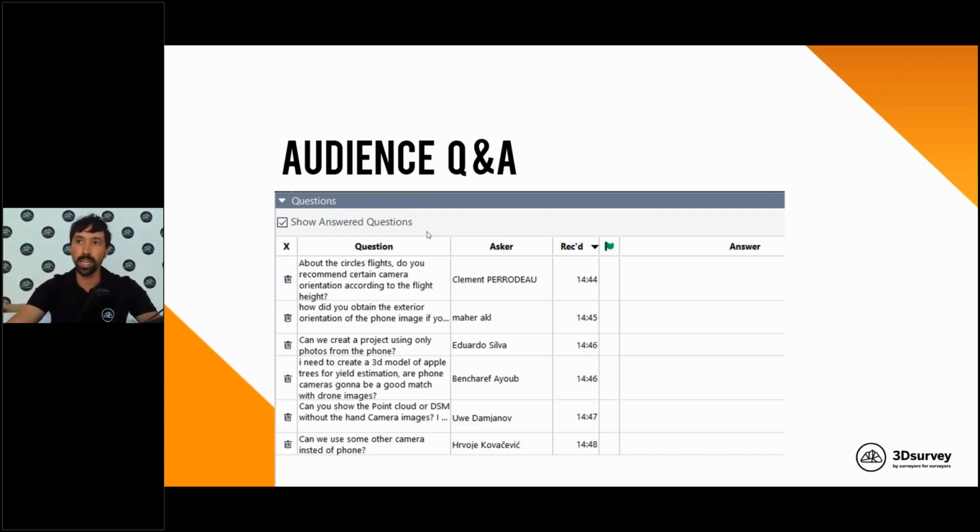You could put 5 targets on the building facades and measure them with a total station or something like that. This would be an area of 5 by 5 meters. Then you trigger about 50 images in a grid, a vertical grid, of course manually, and you do the processing, you do the bundle adjustment and orientation step.